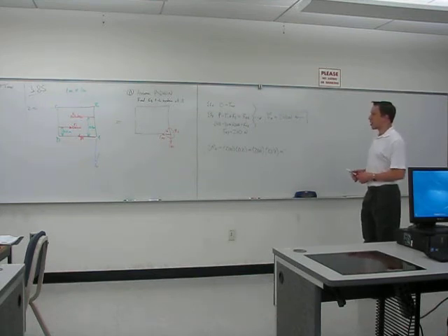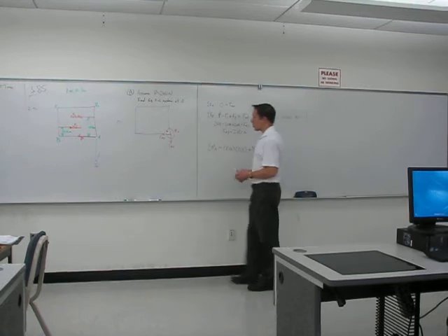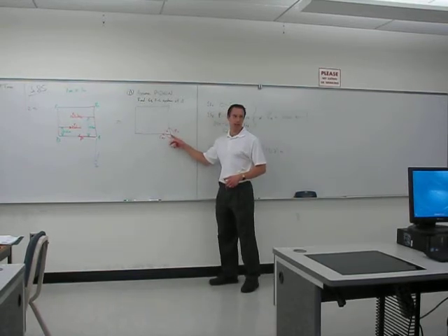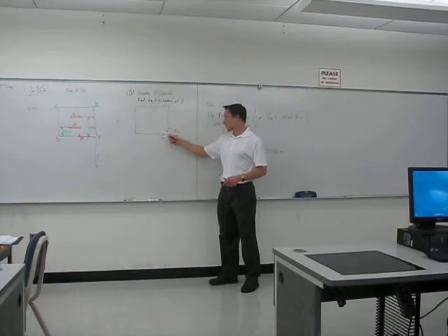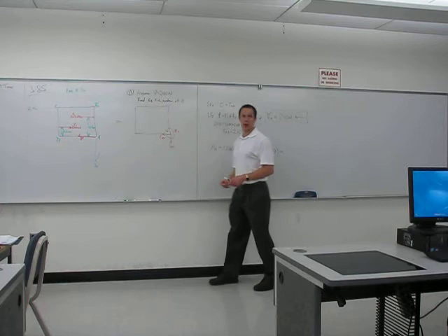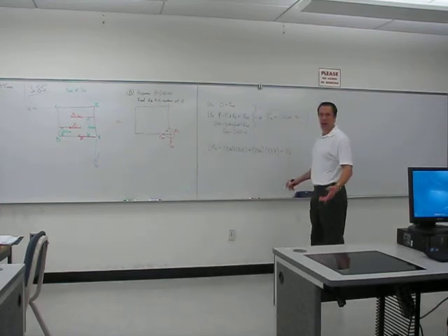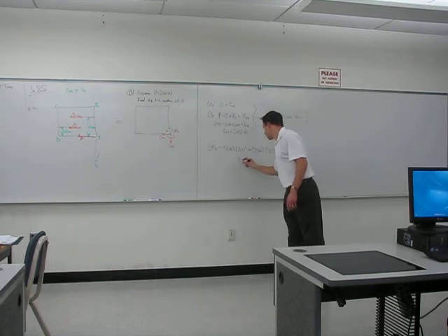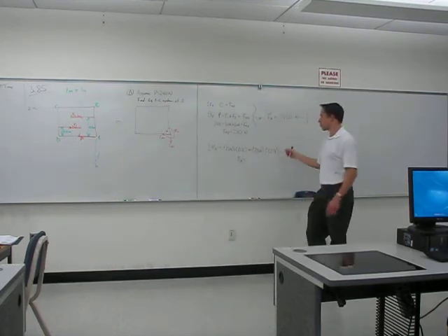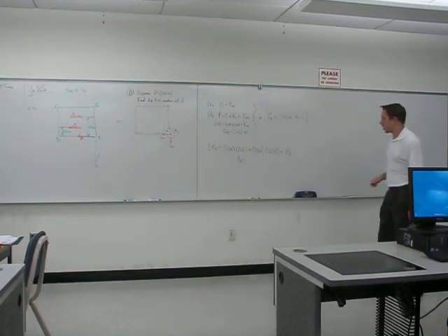So now in the right-hand picture, because we're choosing the point A as the point where we're taking the moments, FAX, FAZ create no moment because their lines of action go through the point A. But we do have the moment vector, MA. So we have MA equal to, we just run the numbers from the left-hand side of the equation here.